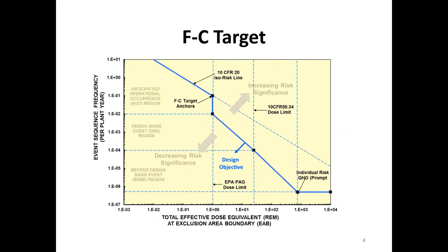Now the second important thing is that, for example, with my seismic category 1 building, I can let it deform a little bit. I permit inelastic deformation. That reduces the seismic load to everything, to my equipment, to my piping systems and everything. So you're reducing it, say, even by 15-20%, and it permeates through the entire plant.